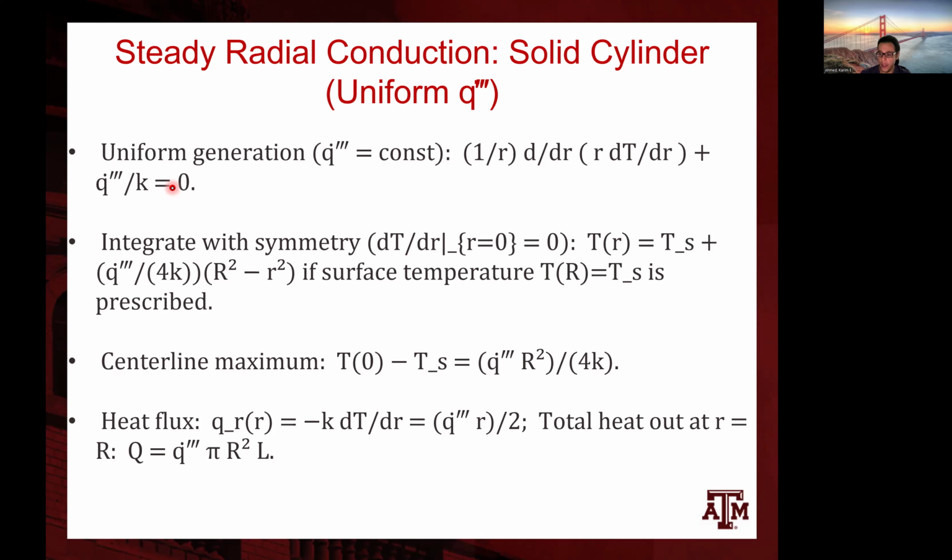If we do that, we can actually derive a simple analytical solution that we will use to demonstrate or confirm or validate the MOOSE solution. The MOOSE solution is a numerical solution. It uses the finite element method to approximate the solution of the partial differential equation. However, to make sure that things are implemented correctly in MOOSE and we are using MOOSE properly, we're going to solve this relatively simple problem using MOOSE and compare the numerical solutions that we get from MOOSE to the analytical solutions that we know are correct and exact.